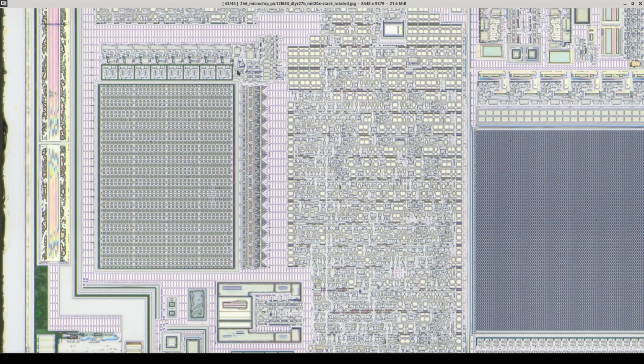of 6-transistor SRAM using a layout that was very standard until about the 180 to 130 nanometer node, when another layout that was more friendly to modern lithography started to become popular. This is a 350 nanometer device, and so this is the exact SRAM bit cell layout we would expect to see. And again, we'll take a deeper dive at this later on, but for now we can move up to